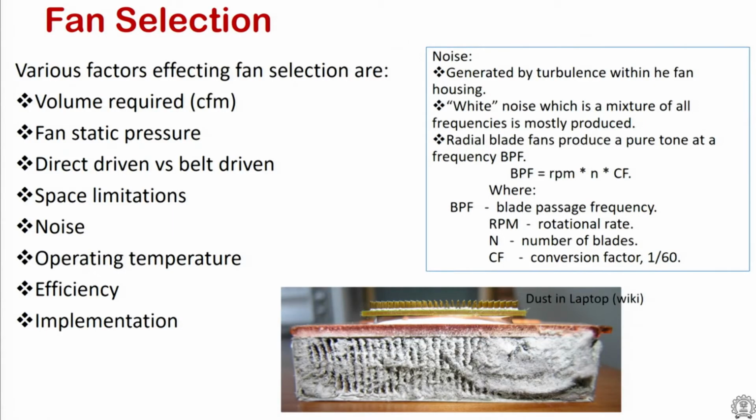So those also need to be looked into, because the fan noise at lower RPM may be fine, but at higher RPM they may start to have squealing sounds due to these tonal sounds from the fan's blade passing frequency. And then the operating temperature: can the fan withstand higher temperatures? So operating temperatures and the type of implementation, whether an axial fan or a centrifugal fan can work, and so many parameters. And for example, what is shown here is an image taken from Wikipedia, and you can